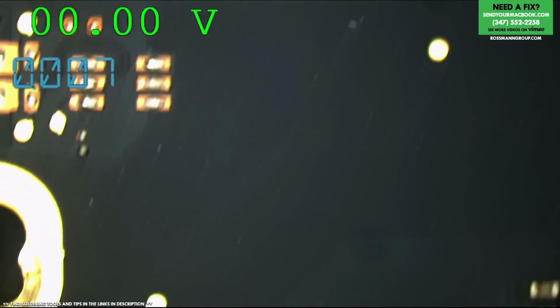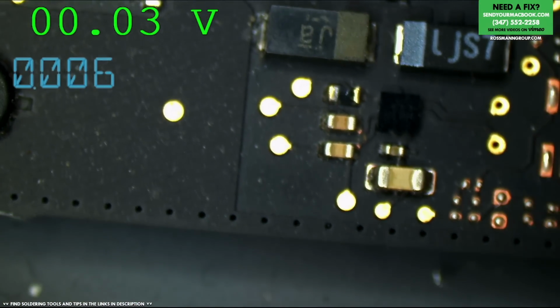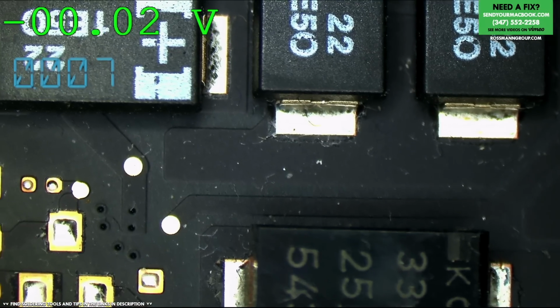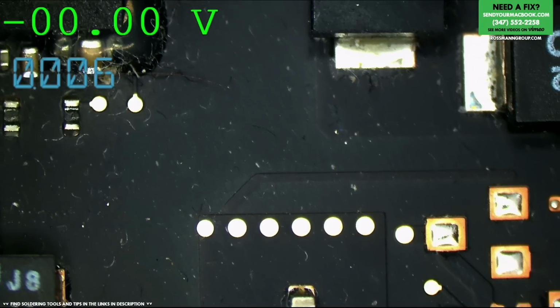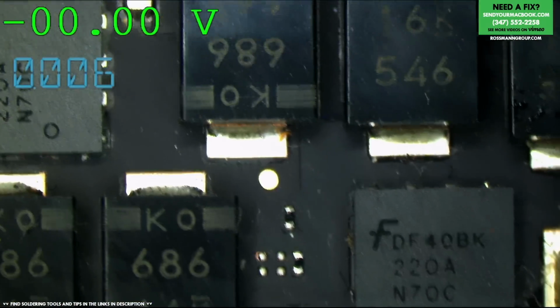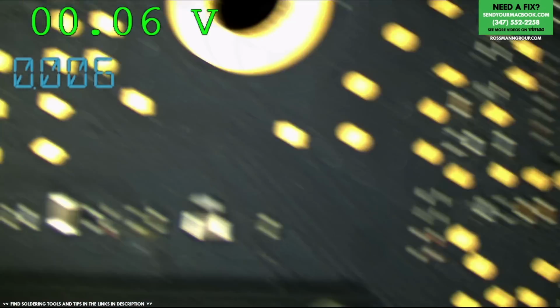Now, if we take a look around here, let's see, do we have any shorted caps? Because often you'll have a shorted cap in the corner that messes up the 5-volt rails, and they'll move back and forth. But I don't think that's the case here, because when you have a short circuit on a rail and PM Sleep S4L is missing, typically it'll be pulsing. So it'll try to turn on, notice a short, and go off, on, off, on, off. And that'll repeat itself. So you'll see it go 30, 30, 30. And that's not happening here. So we're just going to continue our trip around the board.